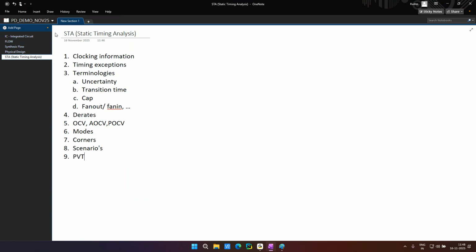I'll give you just a design. For that particular design, where to define clocks, you will be able to analyze it and you will be able to write it. Okay, in this particular STA concept, there is a command in your PrimeTime as well as in your ICC2 synthesis and everything, called check timing.